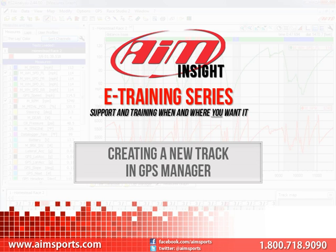There are a couple ways to get information you need to create a new track in the GPS Manager software. The first is to use the Google Earth program, available free on the internet, and get the latitude and longitude values of the start-finish line in the decimal degree format. The other way is to actually make a few laps around the track with your AIM Sports data system. Download the data as you normally would in Race Studio 2, and then from the GPS Manager software, create the new track using your downloaded data.